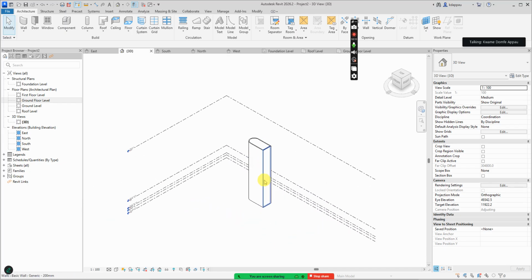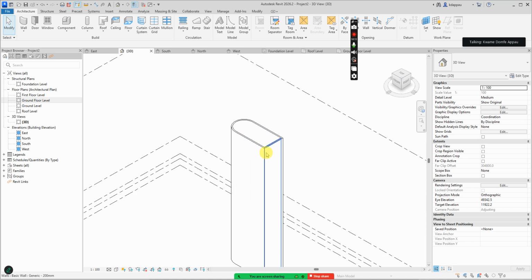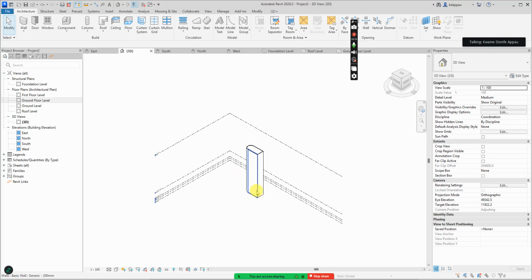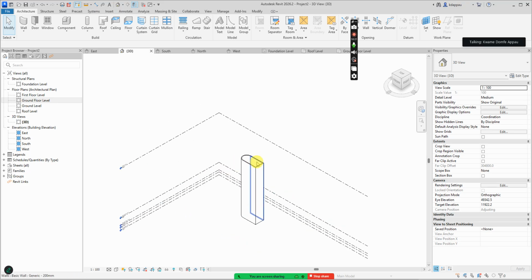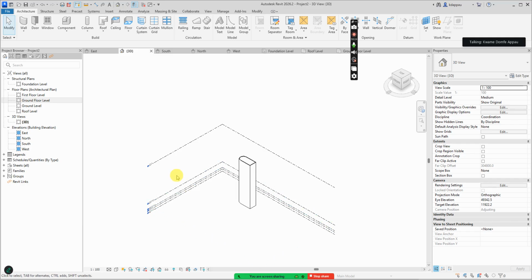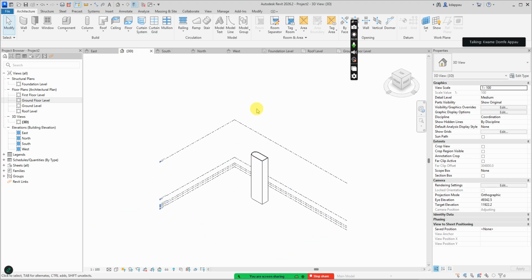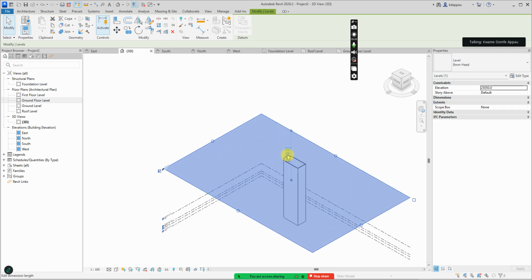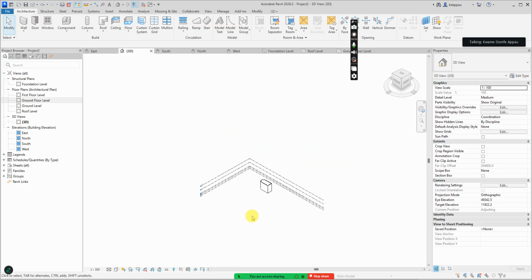If you are doing AutoCAD line work and you are doing a multi-story structure, then you have different line work for elevations, 4 elevations, let's say 4 sections, and there will be the need for you to change one of the levels. Then it means that you have to manually edit all the 4 elevations separately, edit all the 4 sections separately. So the person will complain that I've worked the whole day, meanwhile the person just wasted the whole day. But if you constrain your walls properly, as soon as you update the levels, all the walls will what? Update. So if I select this one and then change it back to 3150, all the walls will update to reflect.